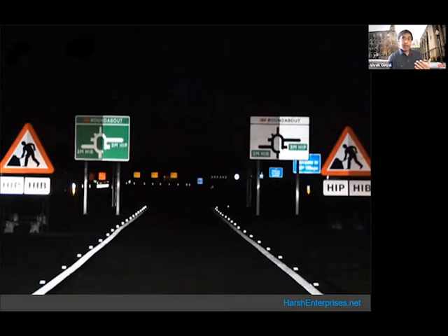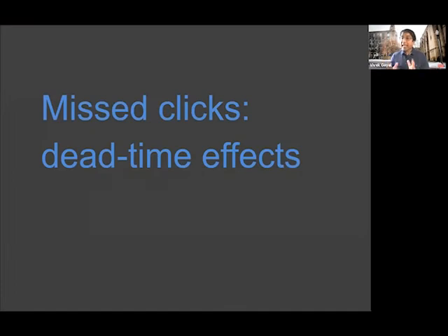But some objects are near and highly reflective, and they may even be retroreflective, like a road sign or a road marker. So in that case, we need to be able to handle very high dynamic range of incident photon flux. Within our field of view at any one time, one pixel may have a very strong return, and another nearby pixel may have a very weak return. Handling strong signals actually requires an understanding of dead time effects in the detectors. This also invites us to introduce some new mathematical modeling.